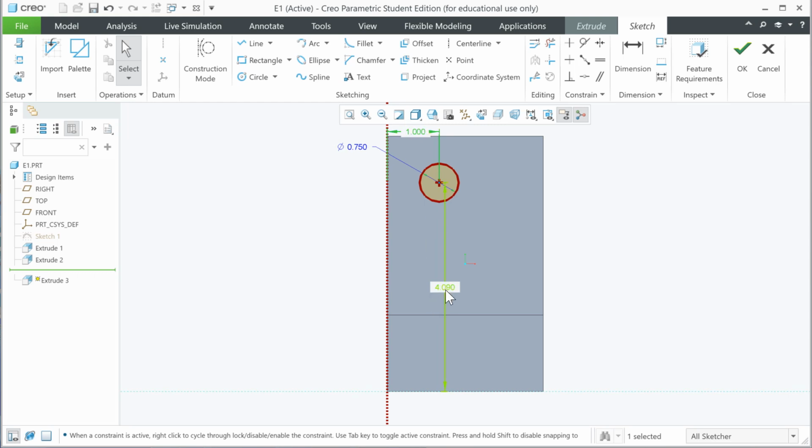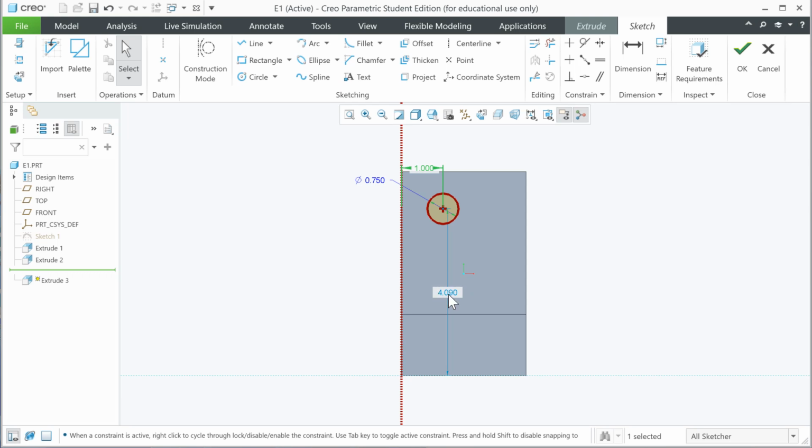However, this 4-inch dimension, maybe instead of dimensioning to the bottom, I want to dimension that to the top. If this is manufactured by someone in the machine shop, it's a little easier to dimension between 1 inch versus extending it the length of the part and different stair steps. So let's go ahead and go to the dimension tool and force one in.